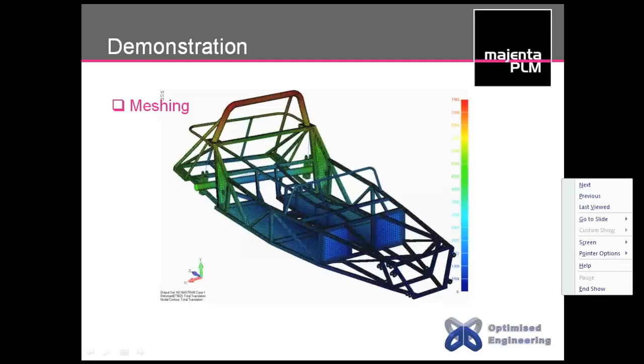But the other thing to think about is that you're not just firing off a CAD model at the auto mesher and seeing what comes back. You can work in that way within Femap. The first demonstration really showed that the auto mesher works very well with 3D geometry. But the fact that you can mesh your assembly or your structure piece by piece and stitch all the bits together, and then adapt the mesh on the fly, is a really new and powerful way of working.